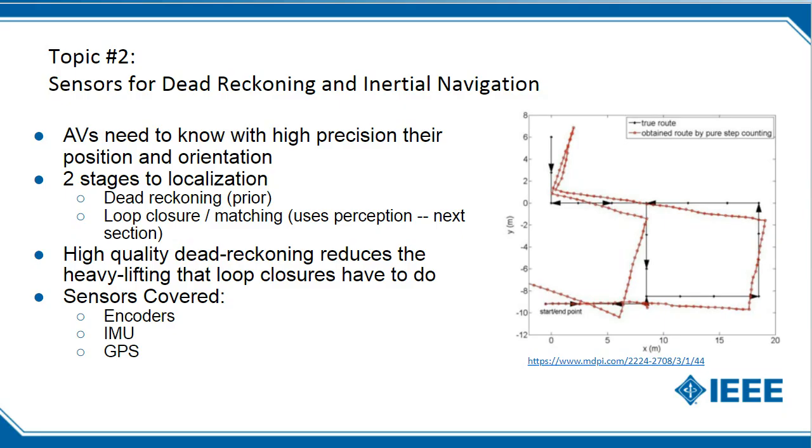There are a number of ways in which we can accomplish that, and typically there are two stages to finding this localization. The first is dead reckoning, wherein the vehicle uses inertial sensors to determine how far it should have gone if there were no disturbances and the sensors were extremely accurate. That includes counting ticks of encoders. It involves checking your orientation with some sort of yaw angle sensor, and you basically have a good guess as to how far you've gone.